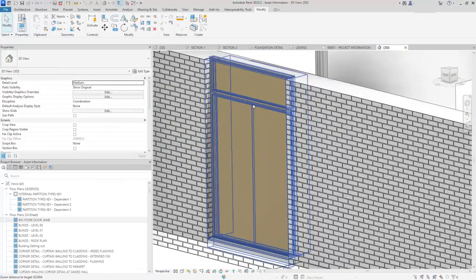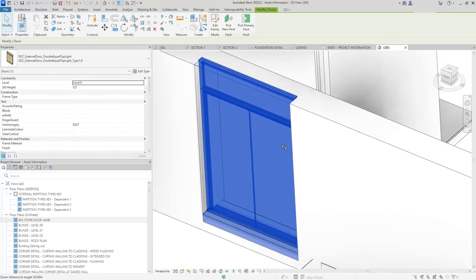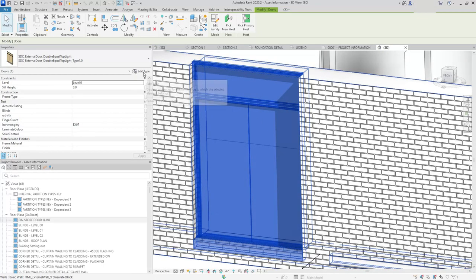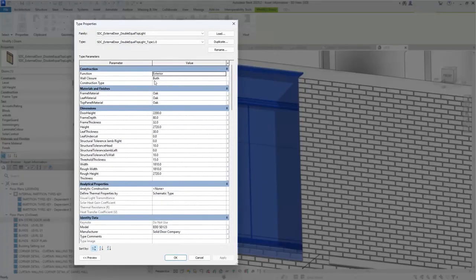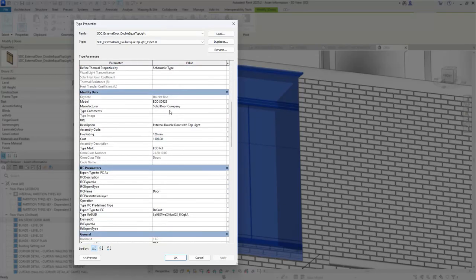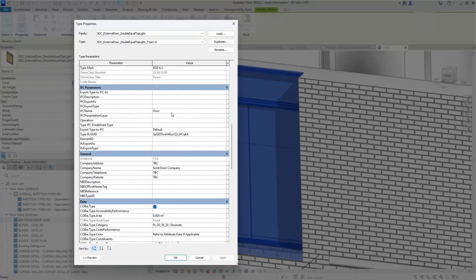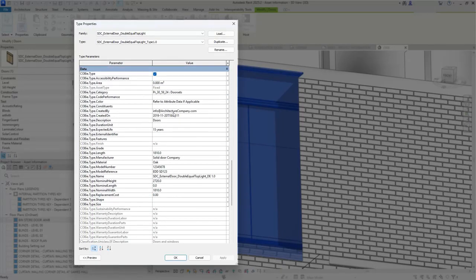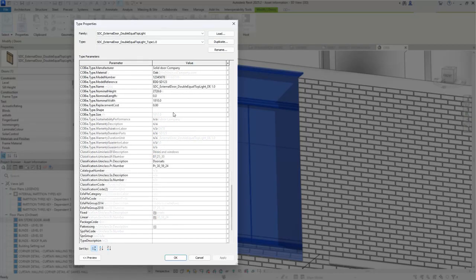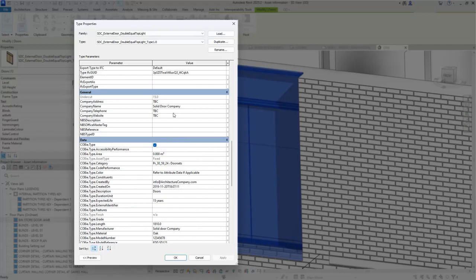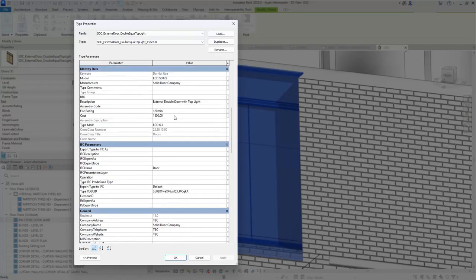During the handover, the common data environment transitions from being a collaboration and design management tool to a central repository for the as-built data and asset information. The up-to-date or as-built BIM model evolves into a digital twin, a comprehensive repository of data for the client of all of the constructed elements in the building, including information such as manufacturer, product numbers, warranty information and contact details for the suppliers, all organised so that it is easily accessible by the client.